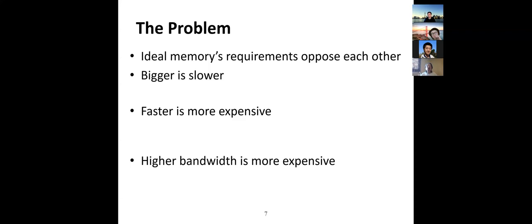So for example, if you buy a 2080 Ti GPU, it's going to use a special DRAM, not the one you use in a CPU, called GDDR6X. And that memory, I don't know, bandwidth-wise, can be 8x, 10x more bandwidth. Latency is more or less the same, maybe even slightly worse, but the bandwidth is so much higher, right? Why is it needed? Because graphics applications need it, because you want to process a lot of things in parallel. Machine learning applications also need it. All of them are very bandwidth hungry. Okay, so as you can see, all these dimensions are conflicting with each other.